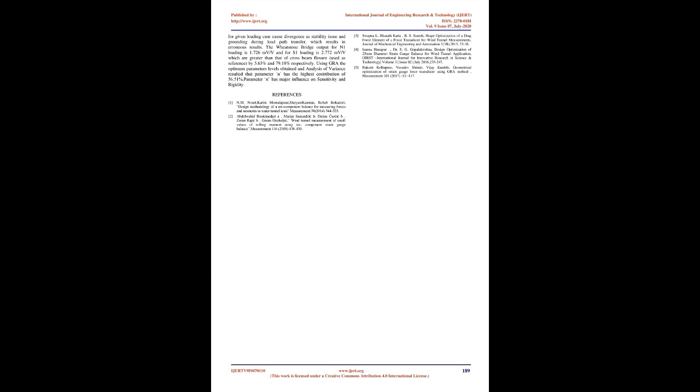These large deformations for given loading case cause divergence as stability issue in grounding during load path transfer, which results in erroneous results. The Wheatstone bridge output for N1 loading is 1.726 mV/V and for S1 loading is 2.772 mV/V, which are greater than that of cross-beam flexure, used as reference, by 5.63% and 79.18% respectively. Using GRA, the optimum parameter levels obtained in analysis of variance resulted that parameter N has the highest contribution of 56.51%. Parameter N has major influence on sensitivity and rigidity.